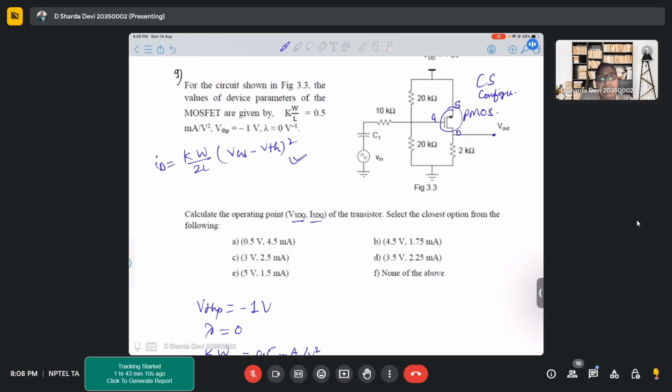The best and easiest way to judge is by identifying the terminals, and you will never go wrong with that. Find out which terminal has input and which terminal has output. Depending on that, the third terminal is common. So here it is common source, since source does not have any input or any output. As simple as that.